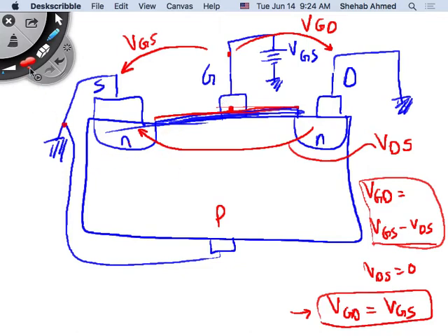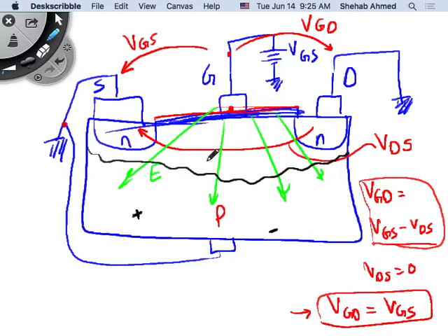We have an electric field. Let me draw an electric field this way, emanating from the gate, okay? What does an electric field do to charge carriers that are majority, P, and then minority charge carriers that are electrons, right? The holes will travel with the electric field, correct? So the holes, these P carriers, will travel with the electric field. This was all P material, so all the P material that I have here has a lot of free holes in the silicon that can carry charge. So I pushed them all down, and I created a depletion layer. So I drew some depletion layer, a zone here that's free of holes.